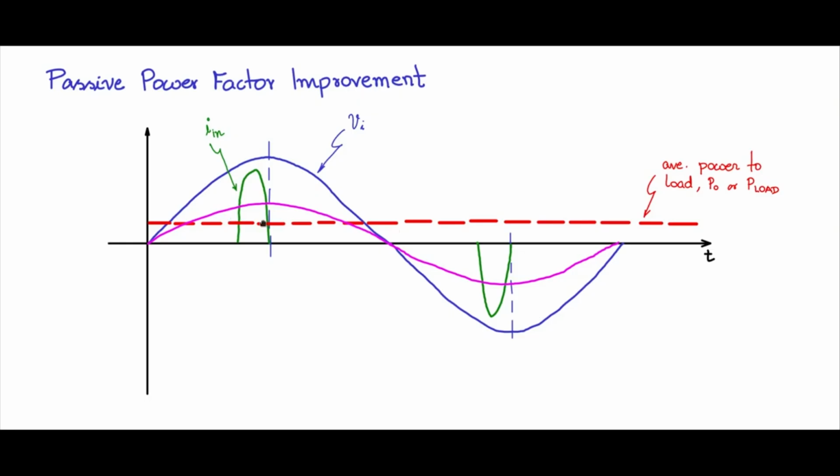The takeaway from here is that as I widen the base of conduction, the peak will start reducing. Now that is the takeaway that we are going to use for improving the power factor. To consolidate this, I am going to show three possibilities on the graph. Let me draw the rectified input source, and let me take the output voltage ripple in this fashion.